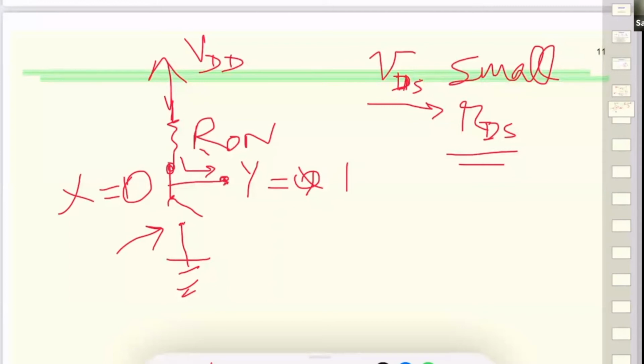The way I understand, or the way I remember it, is that when the gate voltage is high, Nmos is conducting, it's getting the signal through and down to the ground. So it's pulling the signal down. But in the case of Pmos, if I apply the gate voltage, it's an open circuit, it's not letting it go through.